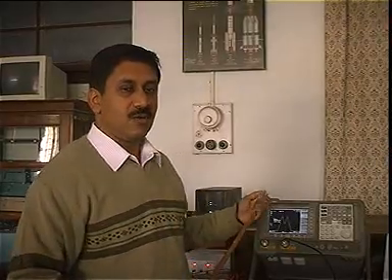Now you may have a question: if the carrier is not being transmitted, how do I demodulate the signal? The point to be noted here is, in a double sideband suppressed carrier transmission, we do transmit the carrier but at a much lower power. We call this a pilot carrier. This pilot carrier is used by the demodulator to demodulate and recover whatever information has been transmitted. Okay, so this is how a double sideband suppressed carrier spectrum looks.